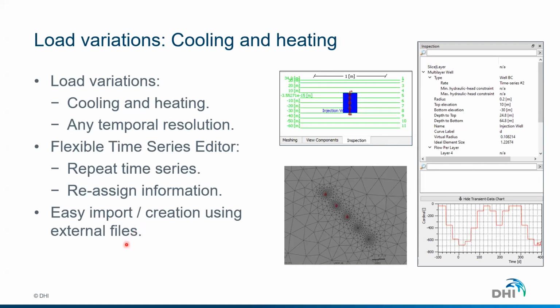Sometimes you are working in heating, sometimes in cooling and heating, so you can apply these different changes in the load by using time series in FEFLOW. We have a flexible time series editor where you can define the resolution of your time series. This could go from hourly, daily, monthly, or yearly resolution. So it's up to you.